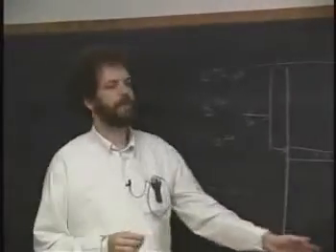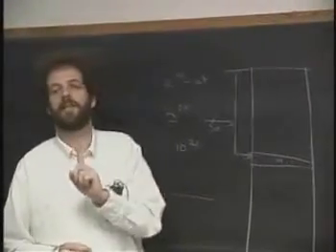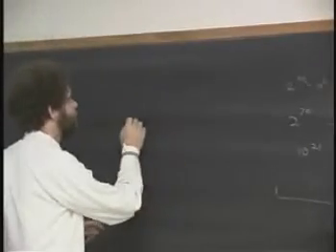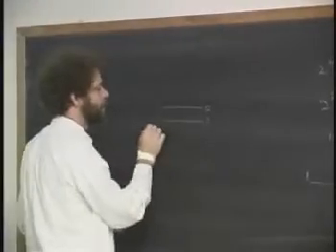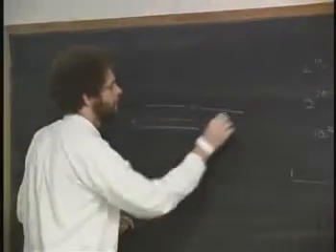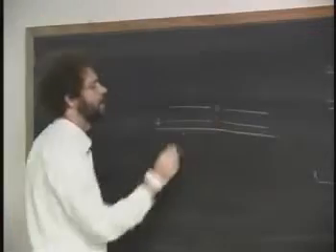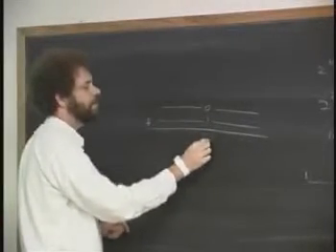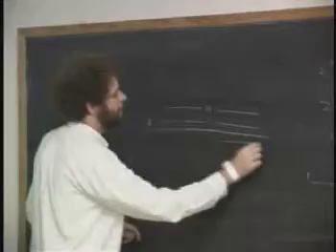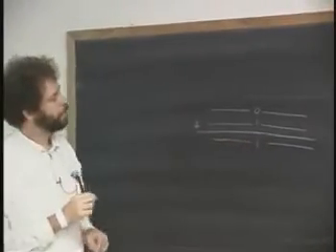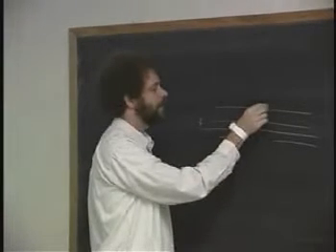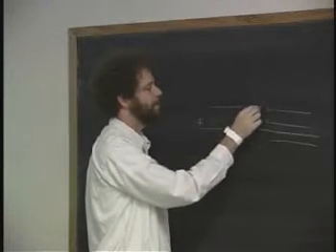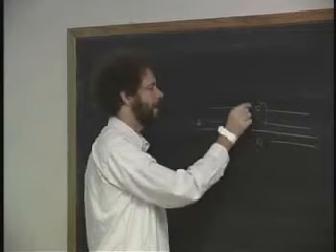So let's just take a look, not at doing 32 bits of ALU, but only 1 bit of ALU. And in particular, if I have a 32-bit number that ends in 0 like that, and another 32-bit number that ends in 1, I would like to sum them. Actually, let's have it not end in 1. Let's just sort of say it goes on and on and on. Then the sum of 0 and 1 is going to be 1, right? And there's going to be other stuff here and other stuff there, except I need to be a little bit careful because it's possible that over here I had a sum, 1 and 1, let's say, which had a carry, of course, that came out of here. And so this is really 1 plus 0 plus 1, which is 0, and a carry got generated out of here.